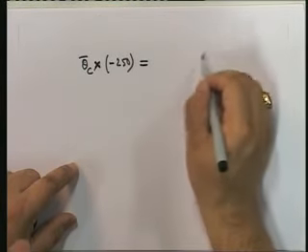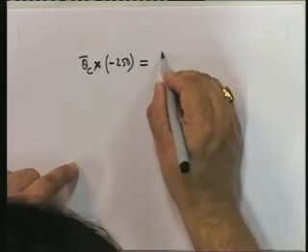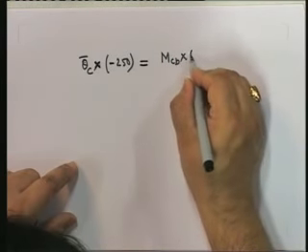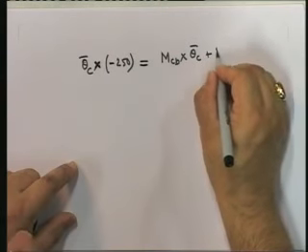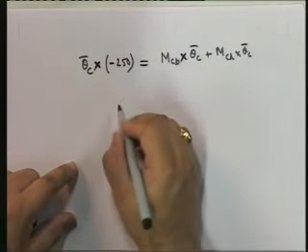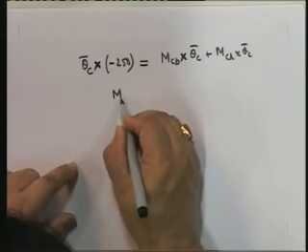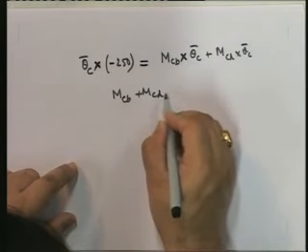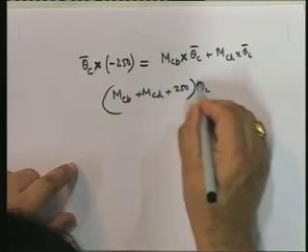All the other external forces, including the support reaction in the joint, do not undergo any displacements. So all of them are going to be 0, and the internal virtual work is going to be MAB into theta AB, which is 0. Theta AB in terms of delta is 0. So you will see that the only terms that exist will be MCB into theta C plus MCD into theta C. None of the others do any work, and so this is going to be MCB plus MCD plus 250 into theta c is equal to 0.